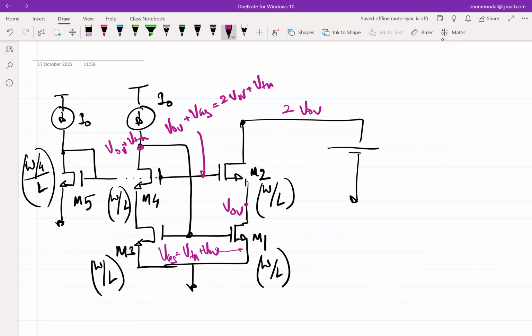Okay, fine, and I found out the voltage VGS. And then I applied that voltage over here and found out the current. But simply we can find out the voltage across this second transistor because the same current is flowing. So there are two approaches. One is you can directly find it out, and another is ignoring the channel length modulation and applying the formula. In both cases, I am getting a different answer. So now the question is, what is the right approach?